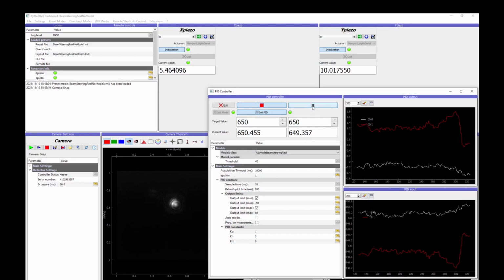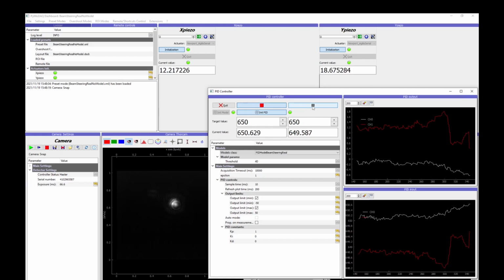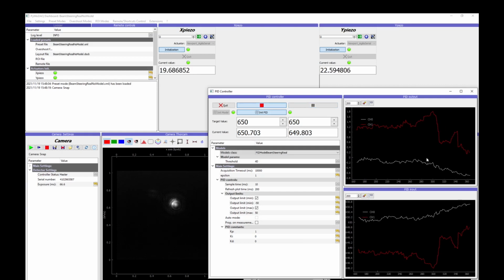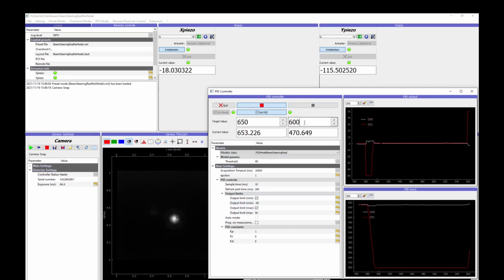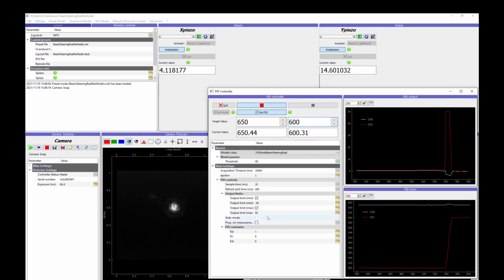And then the system is trying to correct and should go to minimize the error at the PID output. So if I'm moving around, you'll see that the measurement is getting there and stabilization happened there, while here the correction was getting very negative. So I applied -50 on the PID, on the piezos. And you see that there is some kind of saturation there on the correction applied. Well, this correction of -50 here actually corresponds to the output limits I've applied in there. So if I go again in a positive direction, you'll see that the same kind of saturation appears here at 50.